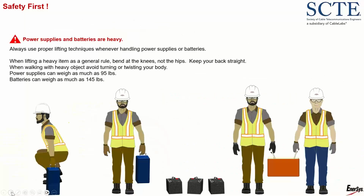Power supplies and batteries are heavy. Sometimes I work with technicians who haven't lifted power supplies or batteries. They don't realize how heavy they can potentially be. You want to use proper lifting techniques and proper carrying techniques when you're working with power supplies and batteries. The heaviest power supply I have seen has been 95 pounds. That's a pretty good chunk of weight. And then batteries, we have outside plant batteries that can weigh as much as 145 pounds each. So when you're out there working them, be careful again when lifting and carrying power supplies and batteries.